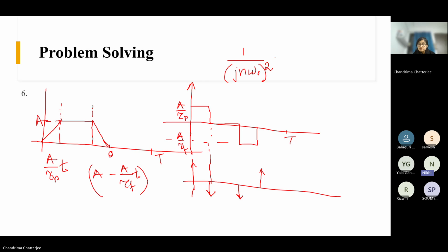So to deliver the project in time, I should be well aware of things, like if I know that this layout will not work, or that the switching frequency of the auxiliary supply will create EMI/EMC issues in future. If I can quantify these things well before the product is finalized, then in the initial phase of the design, you want to cut out all these things, tested individually, because there will only be system level testing on EVs. Before that, I am working exactly at the PCB level.